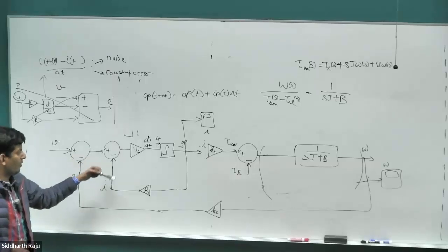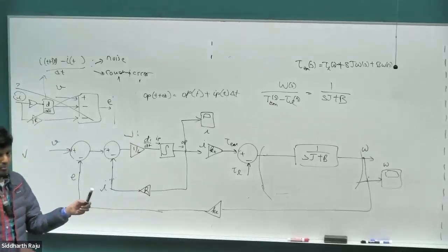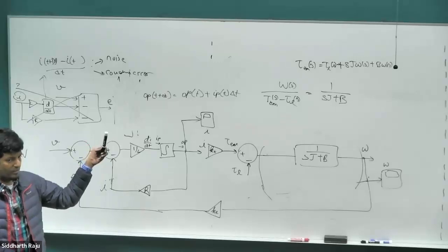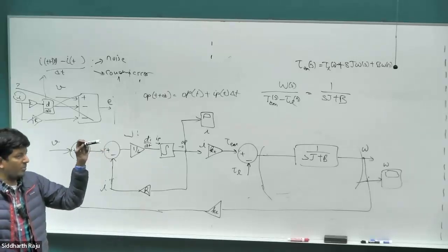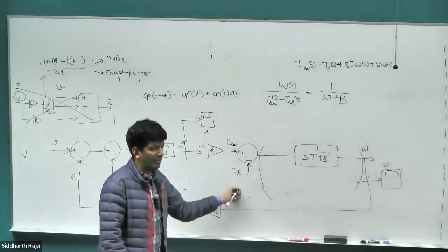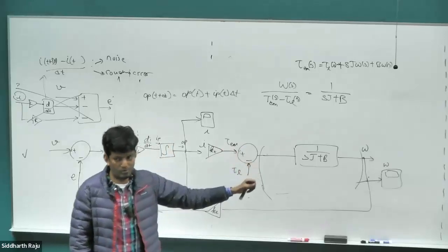But when we go to AC motors, there'll be a whole bunch of parameters and the calculation takes a lot of time. So typically when you run these systems, you'll design a controller and you'll assume that the motor is already operating at a steady state point. You want to see what happens when you apply a step load change in the torque. You would want to do like 1,000 different iterations of simulations to see, irrespective of how the load torque changes, the system is always stable.